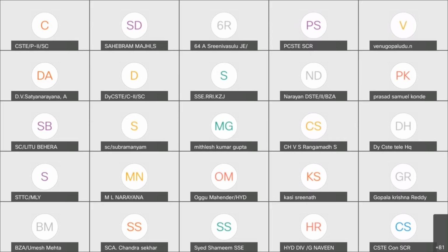This is Ram Prasad, sir, instructor from STTC Malkajgiri. Sir, there are another two problems with respect to the RDSO diagram. Thick web point machine. First thing, the drawing shows the throw slide as straight. They have not shown the L-shaped lug which has to be connected. In the latest drawing that they have issued, the diagram shows that the drive rod is straight. They have not shown the L-shaped lug, sir.